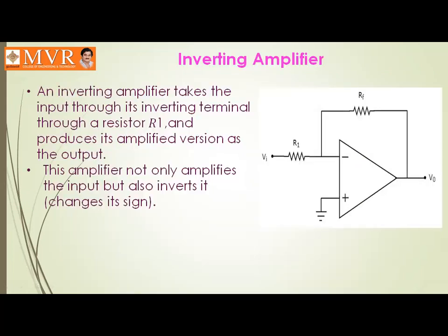Let us consider this node as V1. Nothing will happen. So now we are going to write the nodal equation, that is KCL, for this operational amplifier. Here we already know that we have 0 volts. V1 is nothing but 0 volts. As this is grounded, this is also grounded. Ground means nothing but ground has 0 volts potential, and this inverting input is also at 0 volt potential.